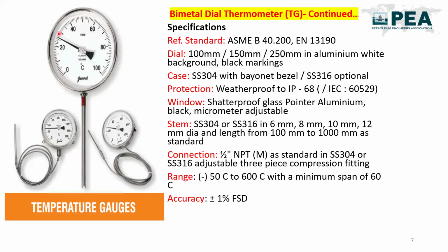Okay, now the protection. Since this instrument is an enclosure, this enclosure needs some protection. What kind of protection do we need? Since this instrument is not connected with any cable wire, there is no such kind of hazard possible. Most of the guys have a confusion, like whether we need to take Ex d protection, Ex i protection, Ex e protection.